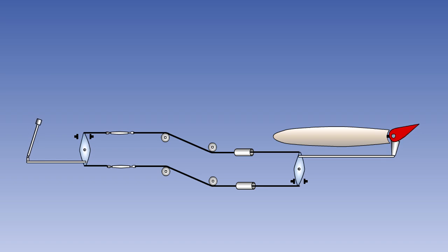The amount of movement of the control surface to either side of its neutral position is laid down, so that the required control can be achieved over the full range of operating conditions. The movement is not necessarily the same each side of neutral. For example, an elevator may have more control deflection upwards than downwards.